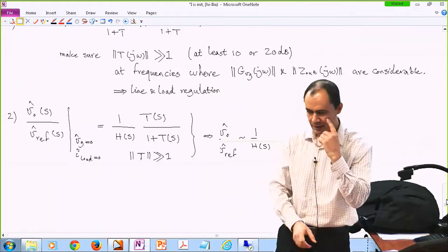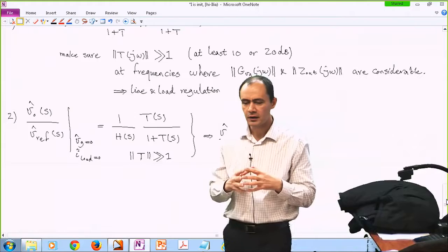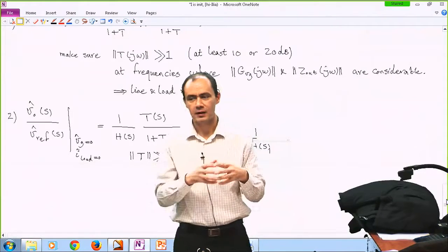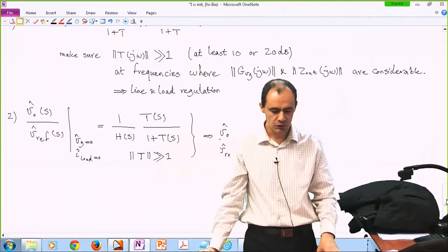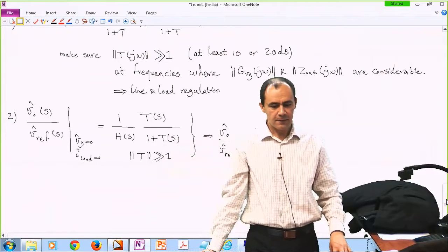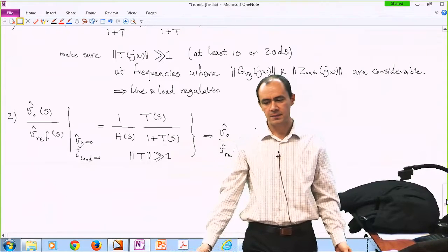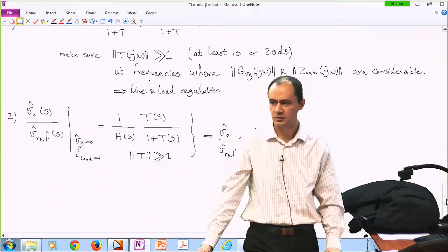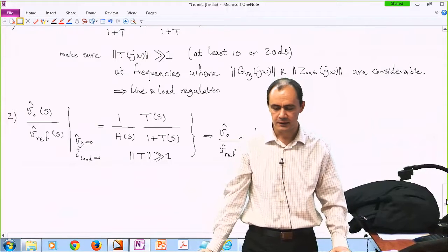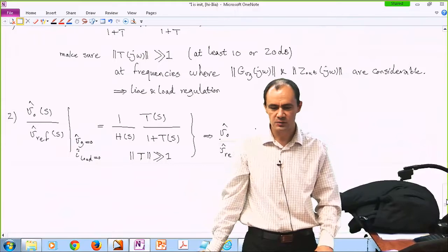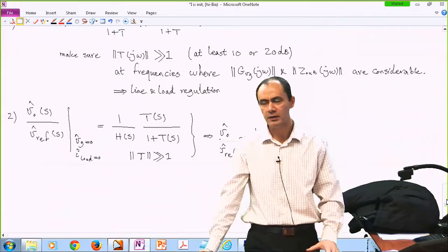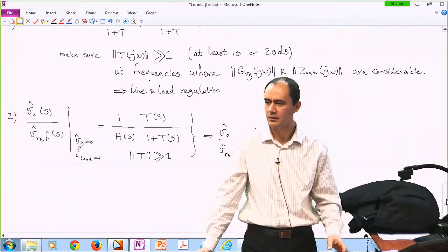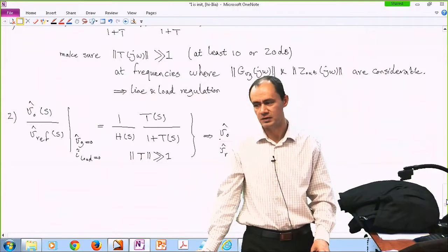Because if you go to the discontinuous conduction mode, the transfer functions that we got here are not valid anymore. It has its own set of equations. I cannot really say if it works or not. I mean, it depends on how much you're deviating from these transfer functions that hold for a continuous conduction mode. And then I would say, generally speaking, no, it shouldn't work. I mean, it works in a sense that if your system was stable before, it might still be stable. But is it the best transfer function possible? Probably not.